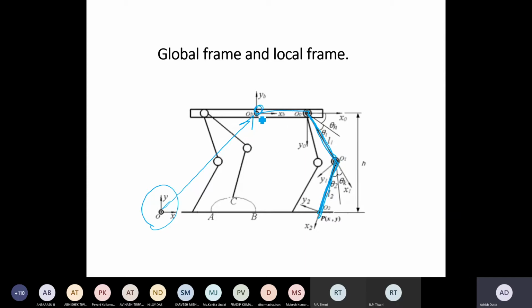Now, if I consider this point to be the origin, then this one is actually something similar to a robotic arm, like a serial arm, I mean. Okay, so we can model this by four serial arms, all of them meeting here. So whatever kinematics and dynamics you have done is also applicable here. The only point being that you have to put the origin suitably so that it can take care of the legs by means of serial arms.